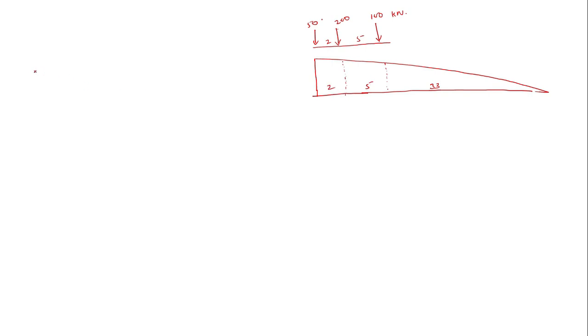So shear force in this case will be equal to 50 into the ordinate here, which is 1, 50 into 1 plus 200 into the slope here, which is again 1 by 40, so 1 by 40 into the corresponding distance 38, plus 100 into 1 by 40 into corresponding distance 33.